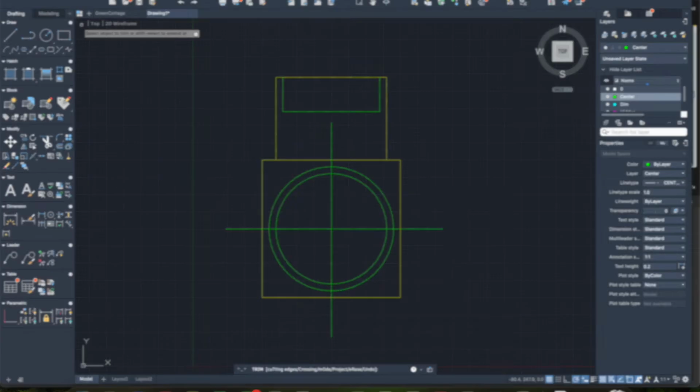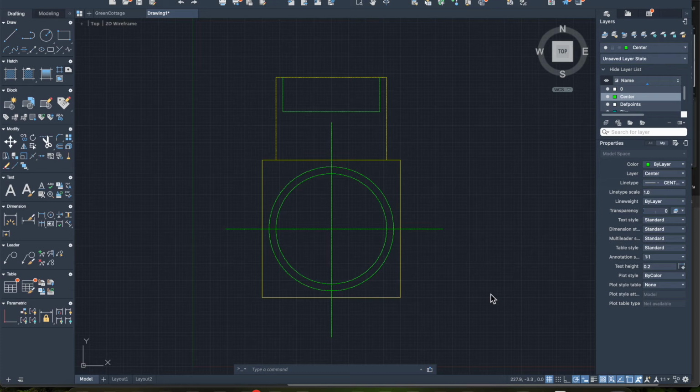Click on it, gone. Design elements, features that you will need to know in order to complete this Lego block. The first one is adding dimensions. So if we go to the dim layer, and then we find the dimensions area, that's the left side of your palette, sorry, left side for me. For you, it's somewhere around this vicinity here, and you will be looking for one called linear.